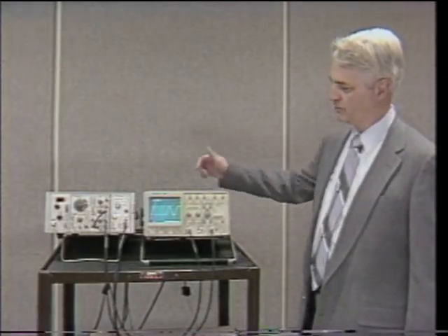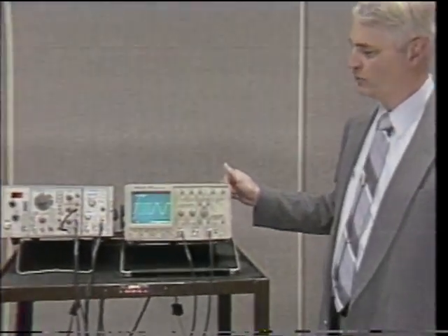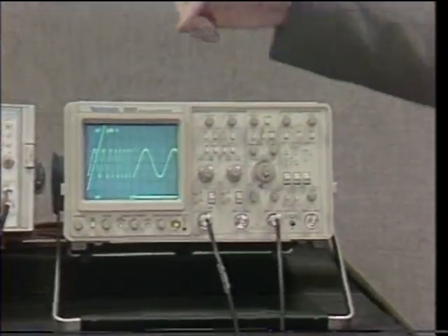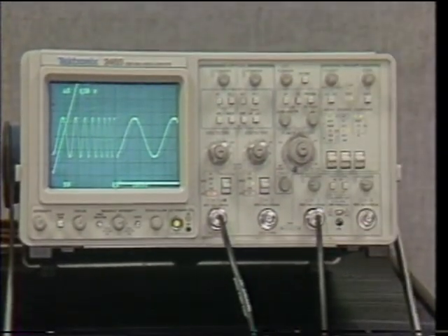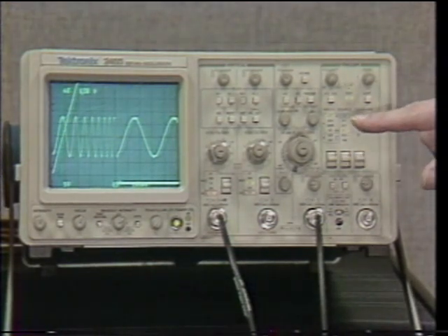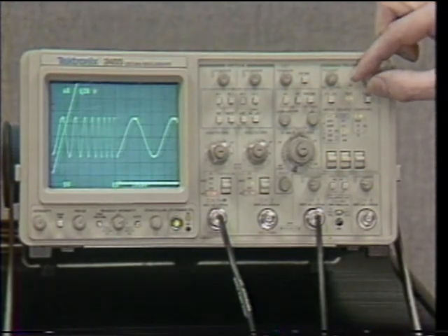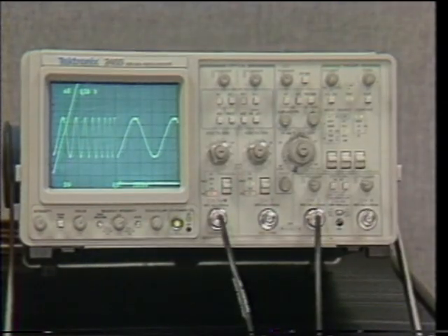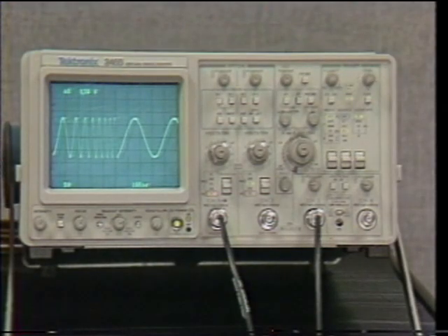Another frequency measurement is a swept frequency measurement. Here we have a swept frequency sine wave, where the frequency is determined by a ramp which we've displayed on channel 3. We're using channel 3 as the trigger source, and with auto level and the level control set fully counterclockwise, we're triggering very near the origin of that ramp. So we are displaying the swept waveform.